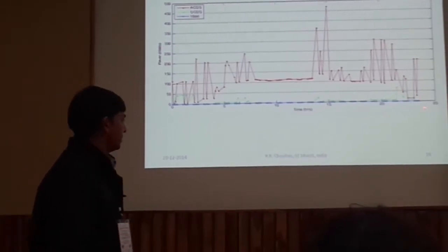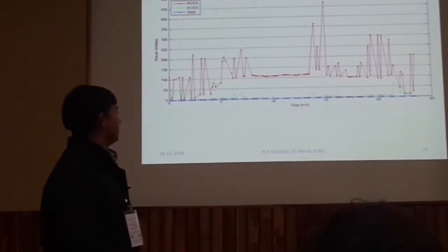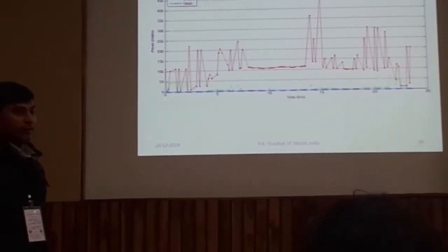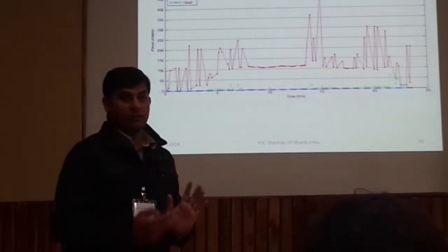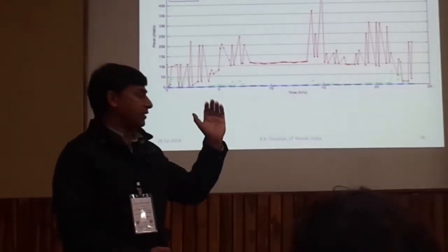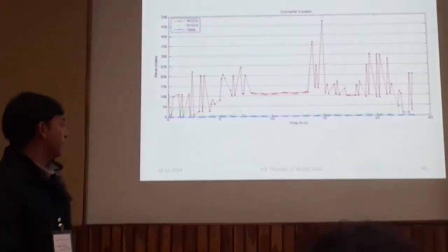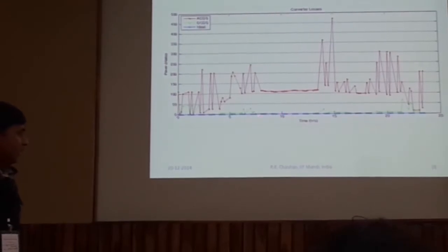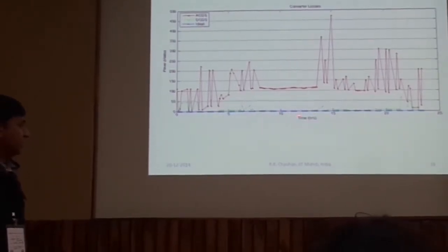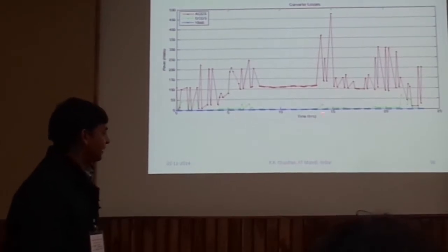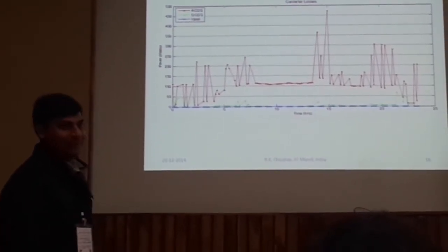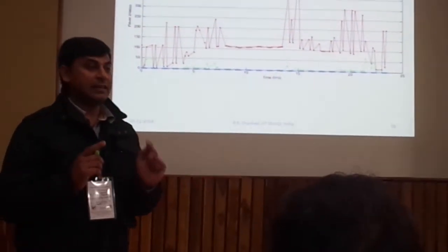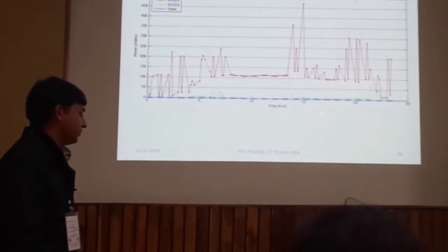These are the power consumptions inside the AC distribution system and DC distribution system. In the day hours, the solar panel is there, which means we are supplying our home by consuming the power from the solar panel. In this case the converter losses are approximately very close to zero. In this other hour the solar panel is also there, but these converter losses exist because I use one single DC to DC converter. So this is the power consumption in that converter.